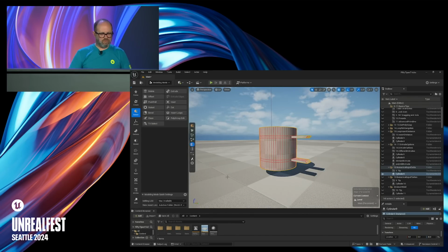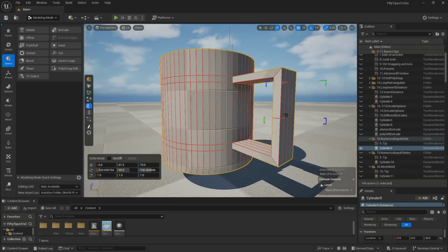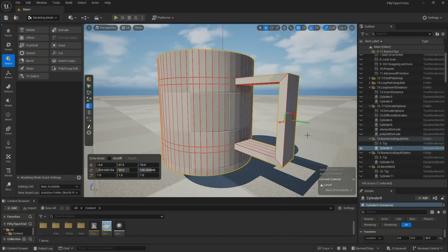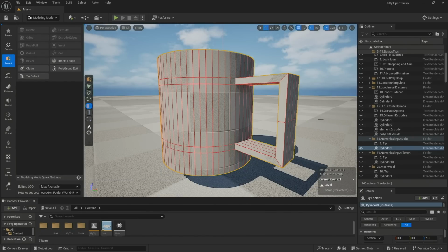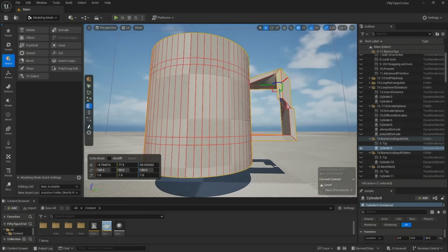I have that shape. Those guys are still selected. And then let's go there. All right. So we have those frozen down. So now the one thing that I have is I still have those individual faces in between. So I'm going to go ahead and delete those faces. And now the problem obviously that we have is, there's a gap in there, which we don't want to have.